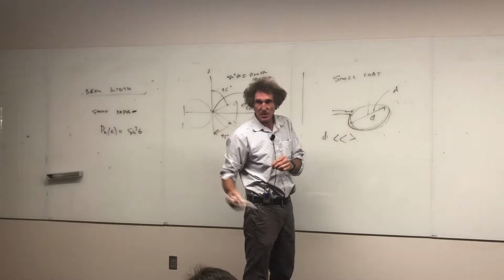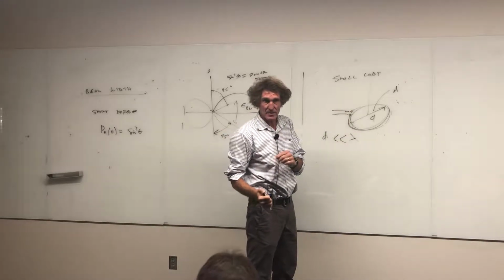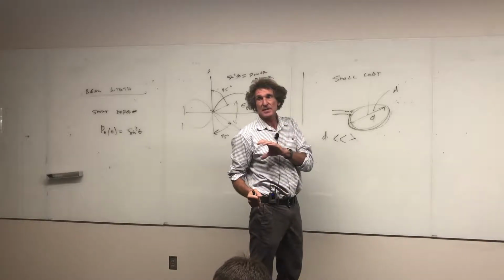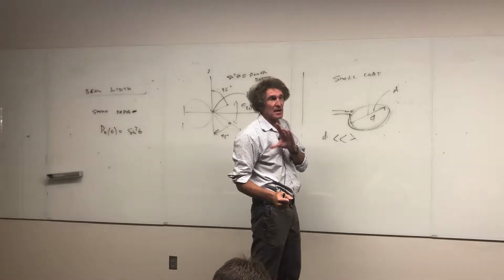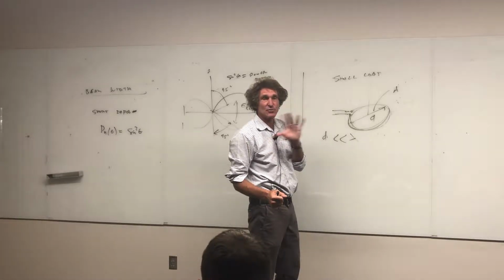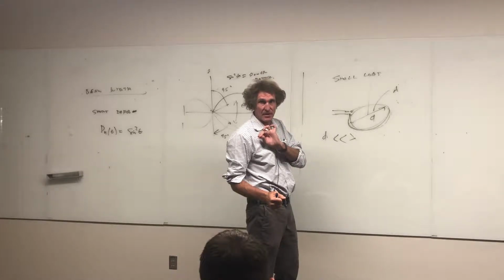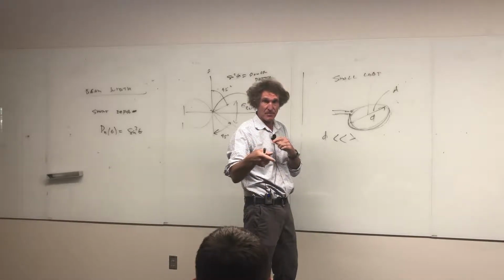Some of this will be clear to you in a little bit, if you don't quite understand what I'm saying. But with these antenna structures, they have something just like anything else that's made of metal. They'll have a natural resonance. At the resonance, you get a full wavelength on there, or half wavelength, and you get a very high input impedance, which you would like. All right, that's something to keep in mind. We're going there. Not yet, though.